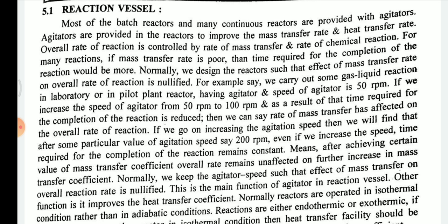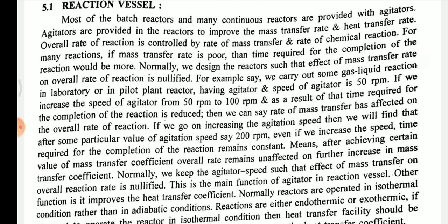That means if we are not using an agitator in the reaction vessel, the mass transfer rate will be low and it takes more time to complete the reactions. So normally agitators are used. Normally we design for the reaction such that the effect of mass transfer rate on the overall rate of reaction is nullified.